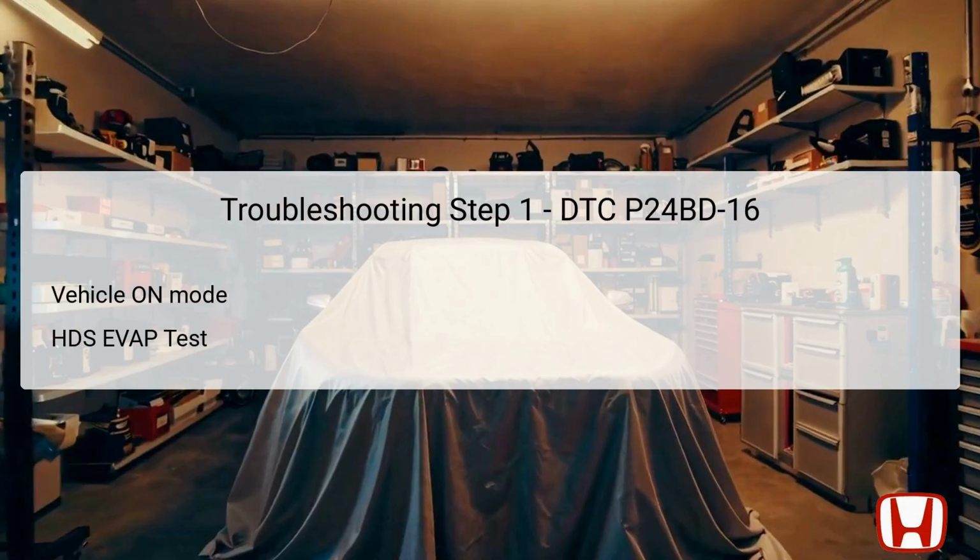If the test results indicate a failure, it confirms that the issue lies within the EVAP subsystem, necessitating further exploration of individual components, such as the CCV, wiring, or PCM. Document the outcomes of this test before proceeding, as it sets the foundation for the subsequent diagnostic processes.